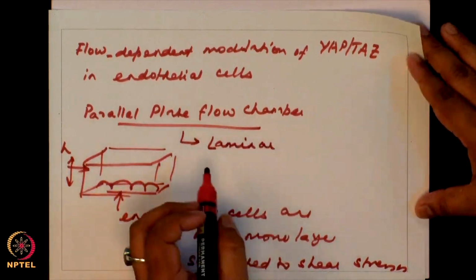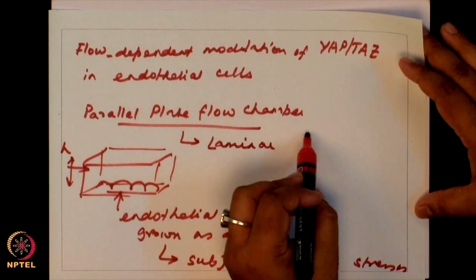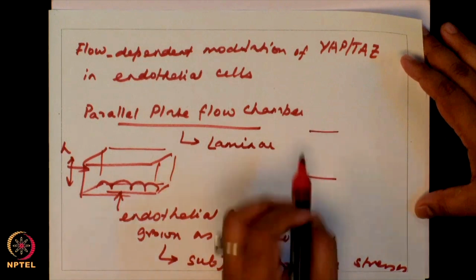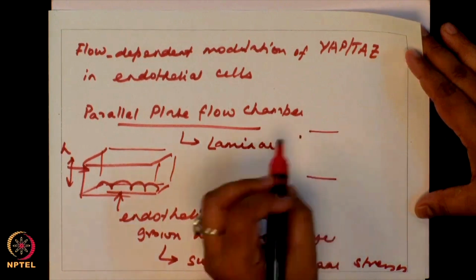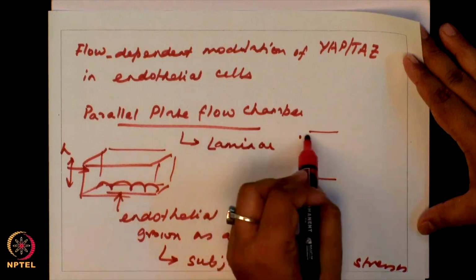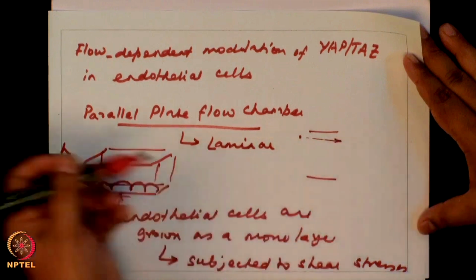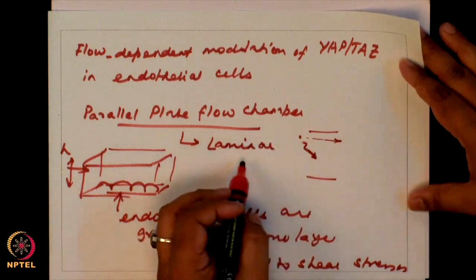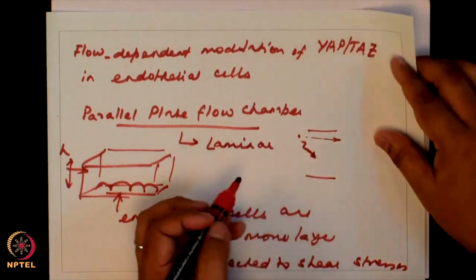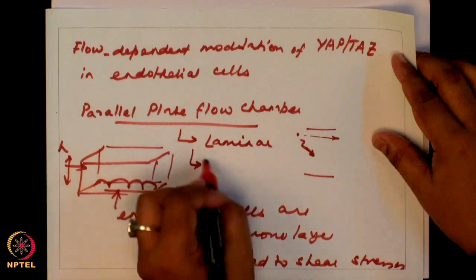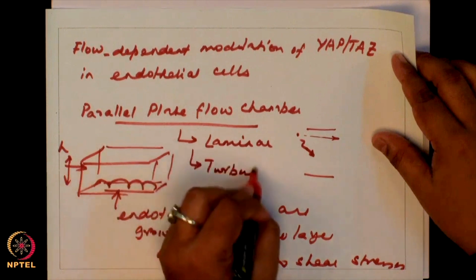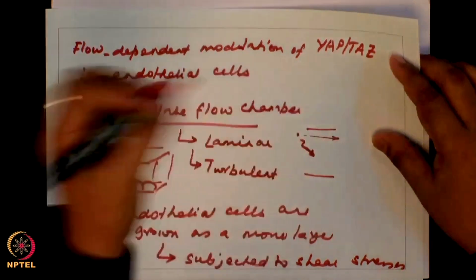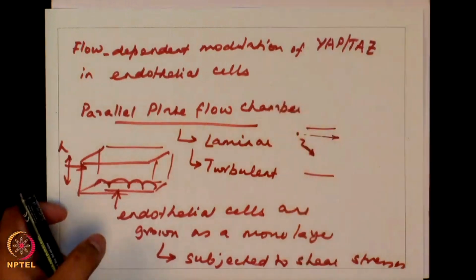In laminar flow, when you have flow there is no mixing. So, in the pipe if you add a small amount of dye at a given point, the dye will travel along that direction and will not diffuse in another direction. This is what is meant by laminar flow. In contrast, you can have turbulent flow where there will be mixing of these particles across this radial distance.